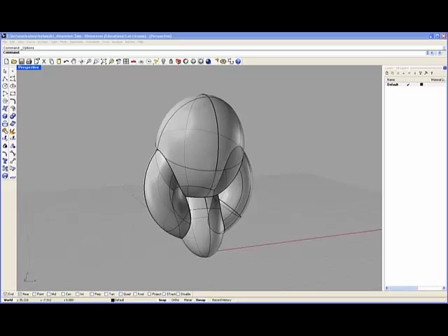When you start to create your waffle structures, the most important thing that you need to do is to make sure that the work is dimensioned properly. It's best to set the dimensions for your work before you cut your waffle ribs, your half lap section ribs into your objects, because it's a lot harder to scale it down later so that you maintain the size of your ribs as you increase the size of your model. So dimensioning your work is very important. And the first step in dimensioning your work is setting up your unit size.